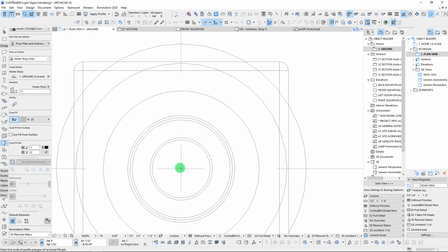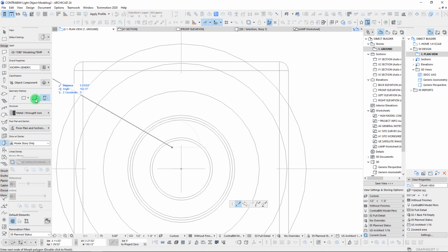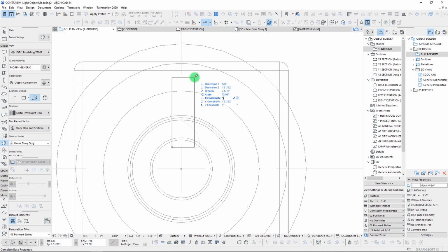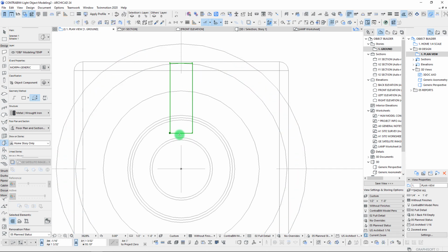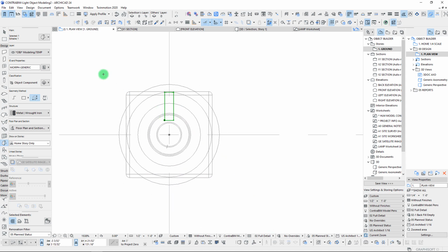So, okay, with this, let's get the general shape going. In this case, we'll actually be using a box once again, and we can go through and offset this to make sure that we have this exactly how we want it. But I'm thinking maybe 5/8 inch in this direction should do it. And we're going to extrude 1/4 inch. And actually, we're not quite where we want to be. We want to actually connect those over.